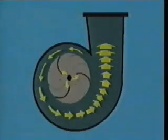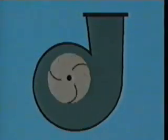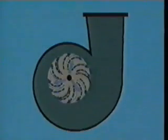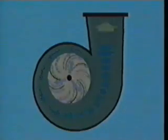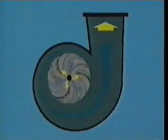Finally, when the gas leaves the compressor, the combination of all these forces, centrifugal force, aerodynamic force, and change in velocity, will have produced a gas discharge pressure that is several times higher than the suction pressure.